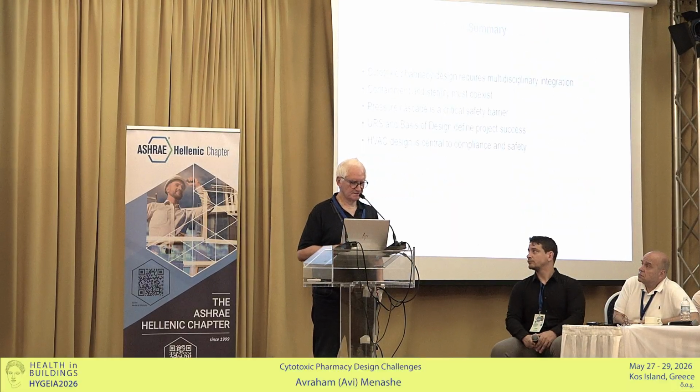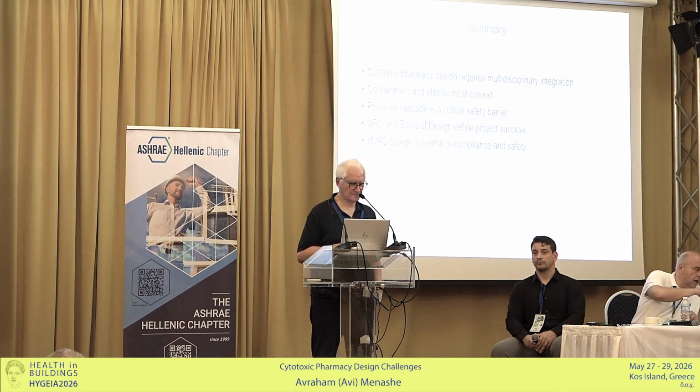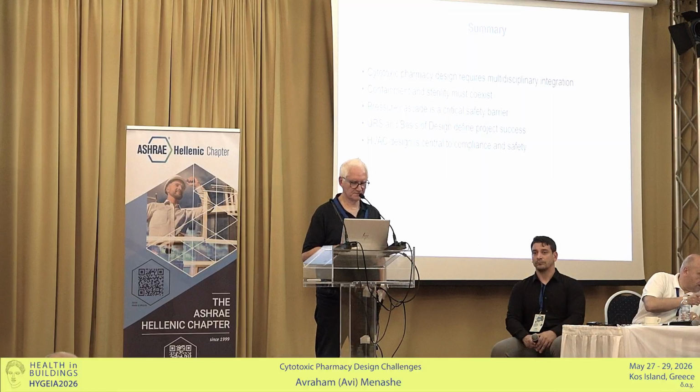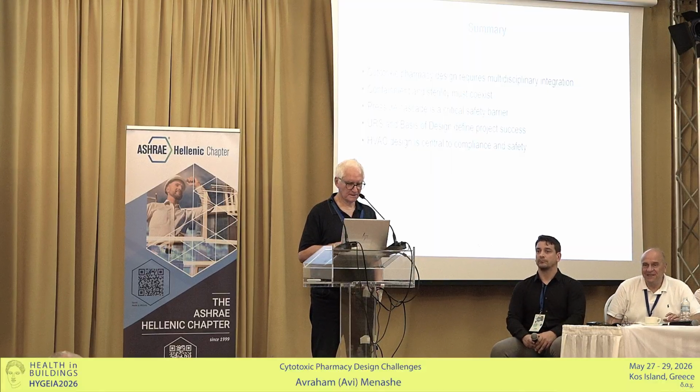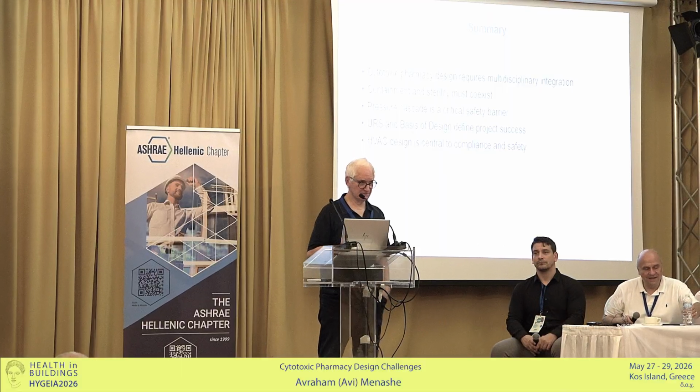And the summary is that cytotoxic pharmacy design requires multidisciplinary integration. Containment and sterile must coexist, pressure cascade is a critical safety barrier, URS and basis of design define project success, and HVAC design is central to compliance and safety. I didn't mention what URS is: the user requirement specification.